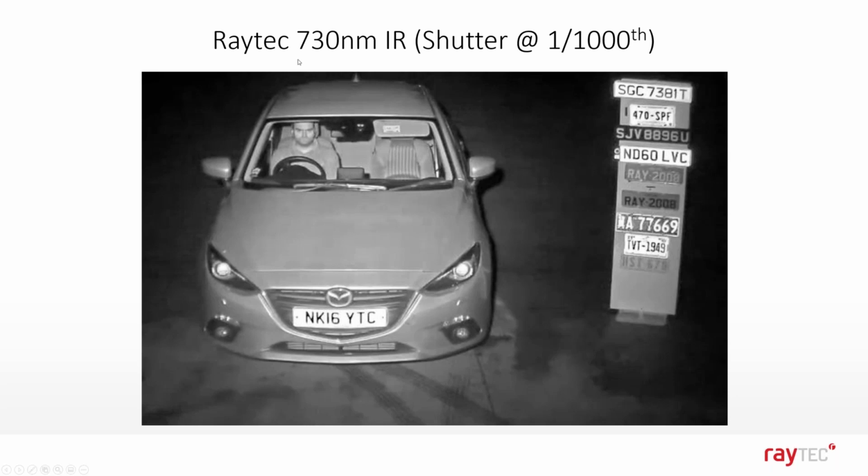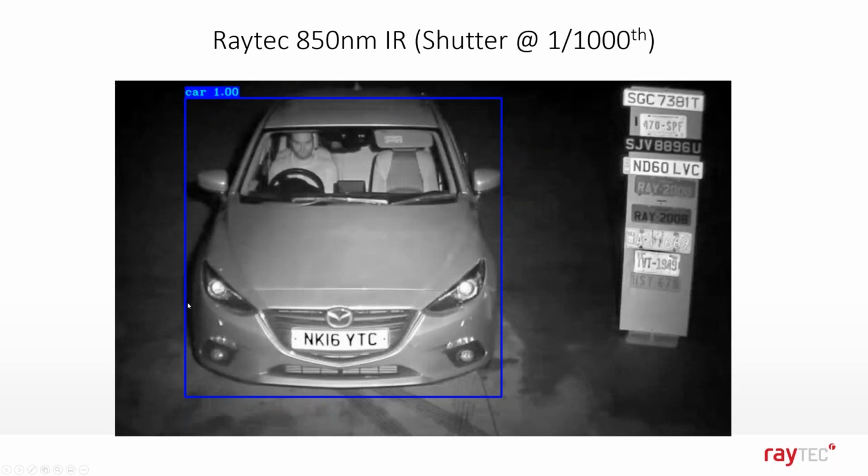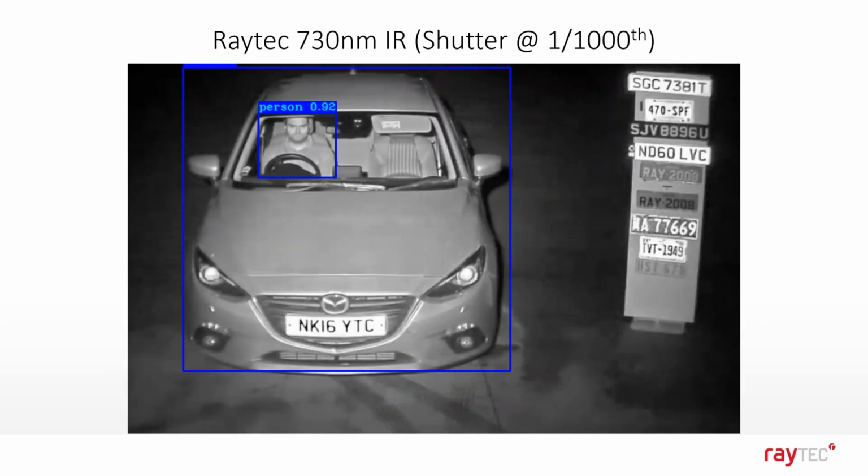So definitely 730 nanometers is what we recommend for seeing through windscreens. And what we'll do as well, I ran these same images through some analytics. So object detection analytics, it classifies, it detects the objects, whether it's a car or a person. That's all I set it to. So it detects the car at 100% accuracy, but it's not finding the person. So even though very little difference to the human eye, we can see that we'll go 730 nanometers, and the analytics went from not detecting it to 92% confidence that that is a person inside the car.